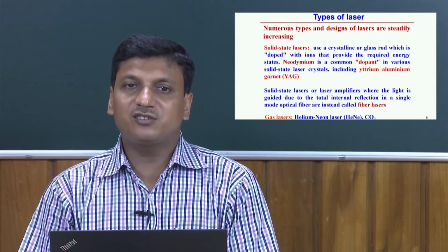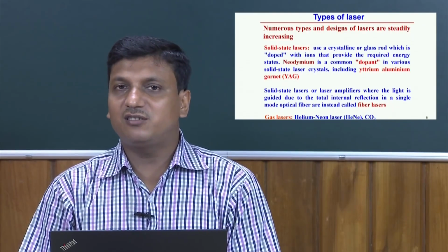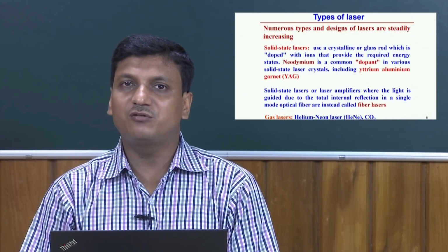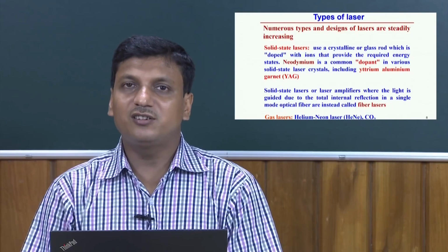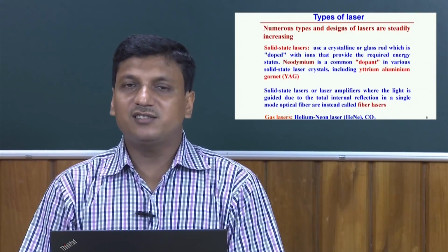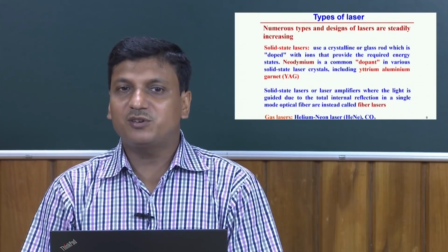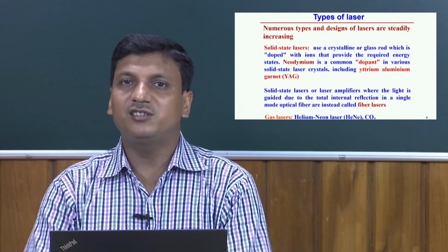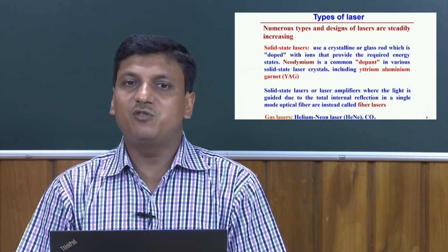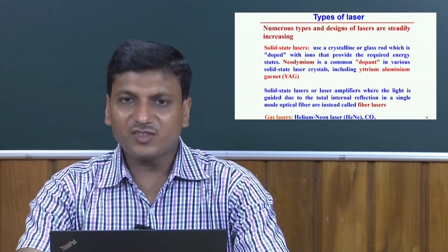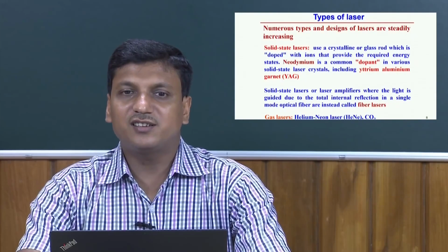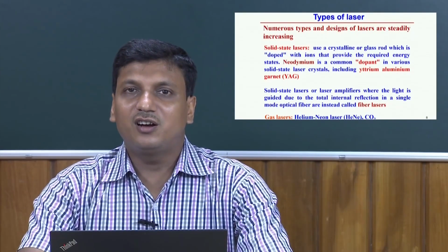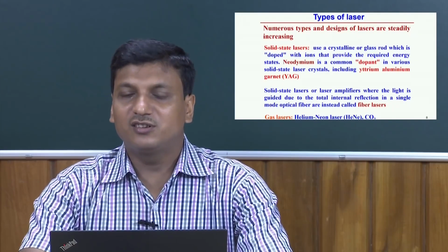Of course, the fiber laser is a solid state laser, but in this case the only difference with respect to the others is that the optical fiber can be used to guide and conduct all the internal reflections. So, in that sense the fiber laser, with respect to the Nd-YAG laser or other solid state lasers, can have a more concentrated light. Another type of laser is the gas laser, and we commonly use CO2 gas lasers or helium neon lasers. So, here the lasing medium is gas.